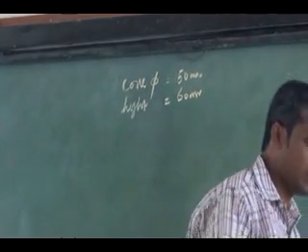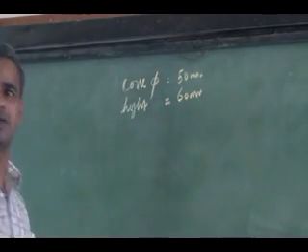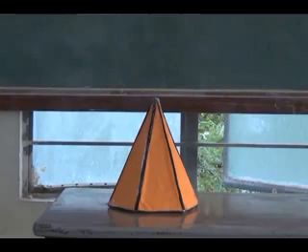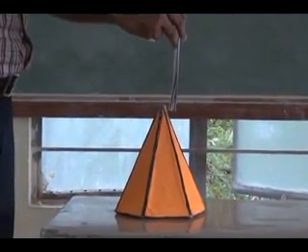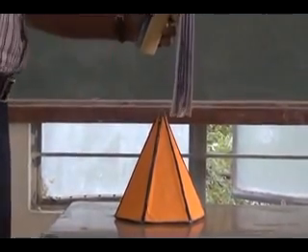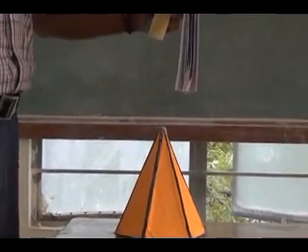So we missed one category. If a cutting plane is perpendicular to both HP and VP, and we cut the cone with a cutting plane like this, what is its orientation? To which plane is it perpendicular? Perpendicular to both, HP as well as VP. So where do I have to represent the cutting plane?